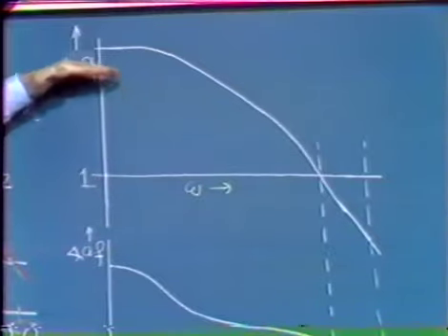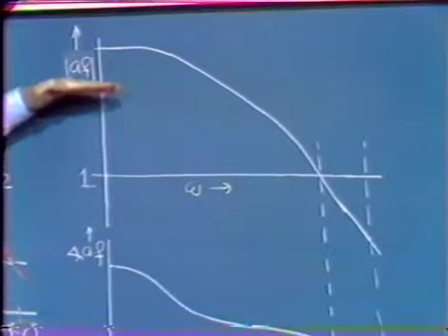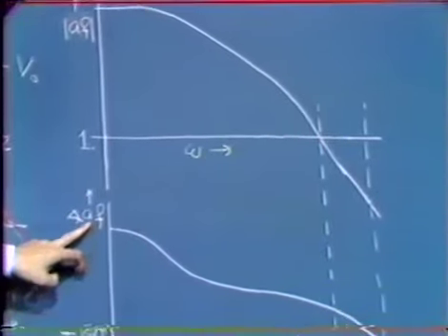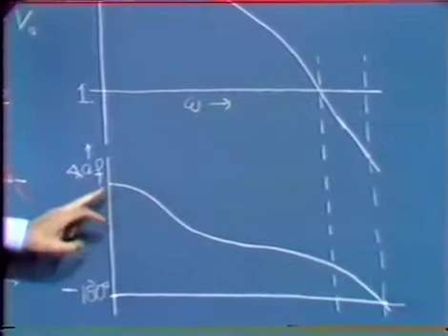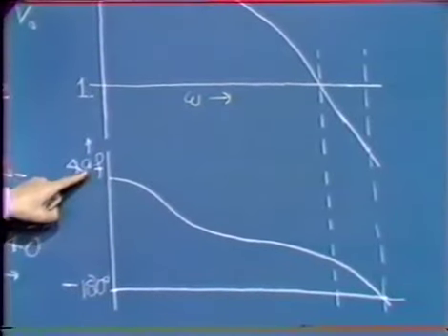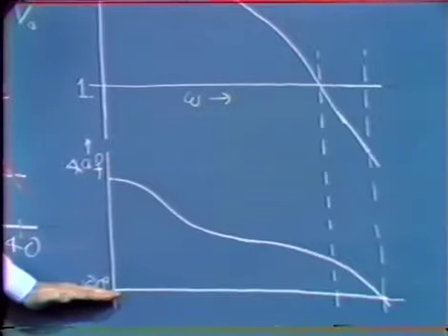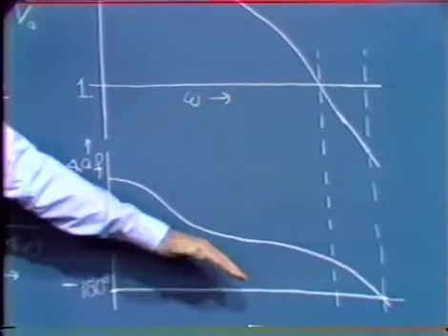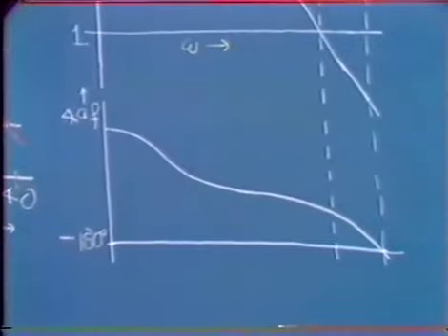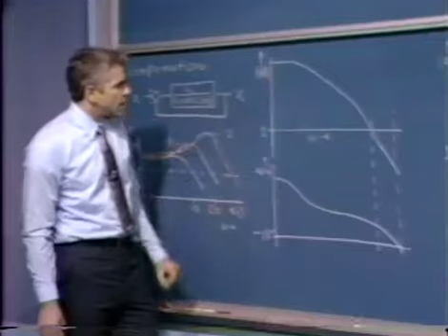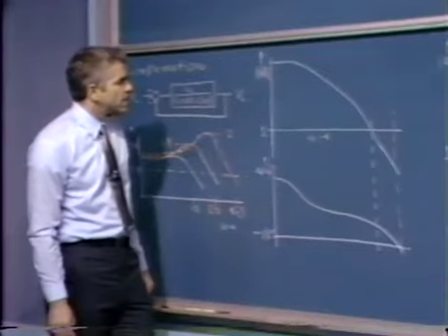And we'd have logarithmic spacing here, 10, 100, 1,000, or whatever. And similarly, on the same common frequency scale, we plot the angle associated with the AF product, possibly going from 0 degrees to minus 180 degrees and then beyond. So here we have the usual Bode plot presentation for an AF transfer function.